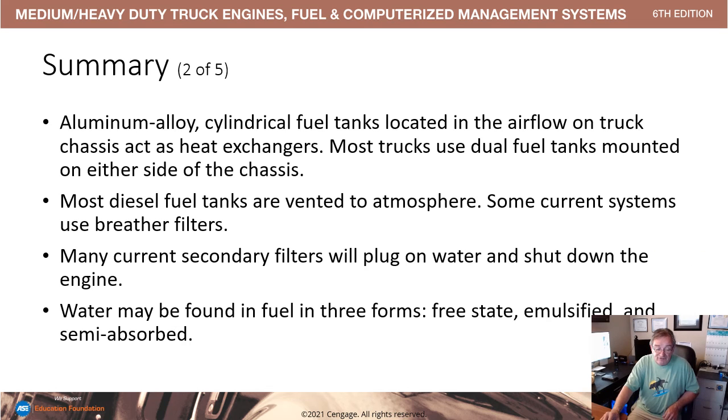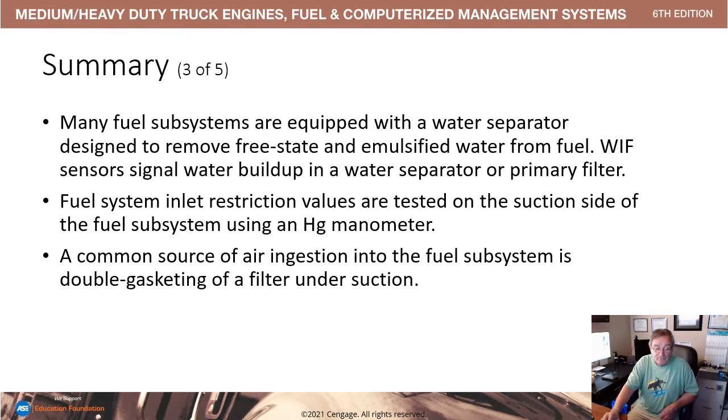Water may be found in fuel in three forms: free state, emulsified, and semi-absorbed. Many fuel subsystems are equipped with water separating fuel filters designed to remove free state and emulsified water from the fuel. The WIF, water in fuel sensor, will signal water buildup in a water separator or primary filter, and it will send a fault code to the ECM, and that will appear on the dash for the driver to see.